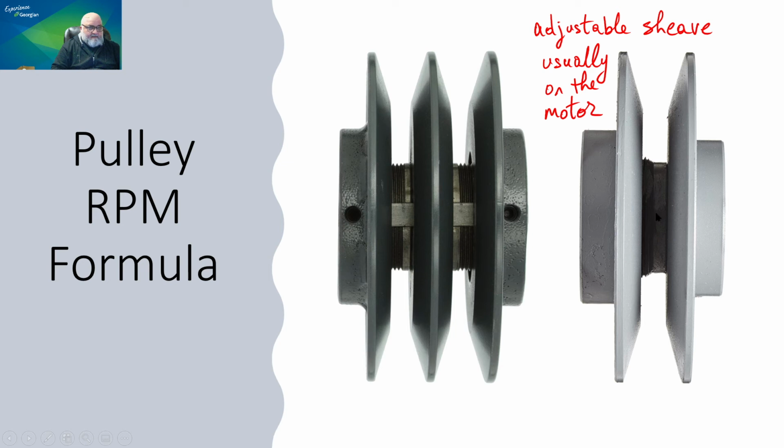And again, closing up means that you are making this distance smaller, so you are increasing the diameter. So let me write it here. Closing up makes the diameter larger, because you are making this distance smaller, then the belt will have to move up and increase the effective diameter.